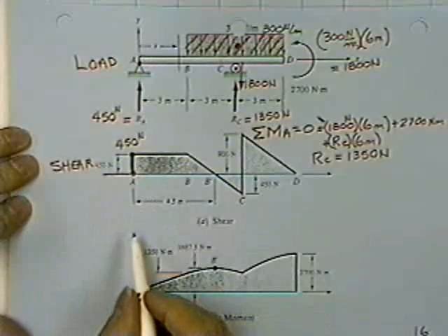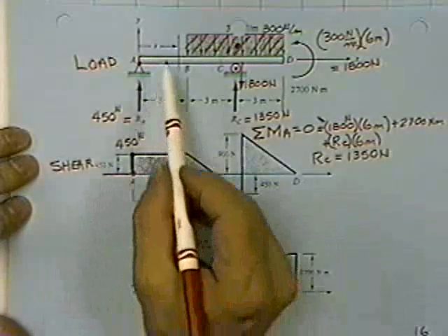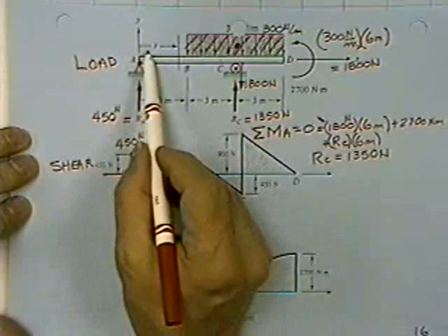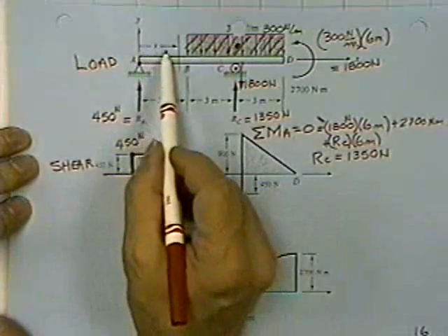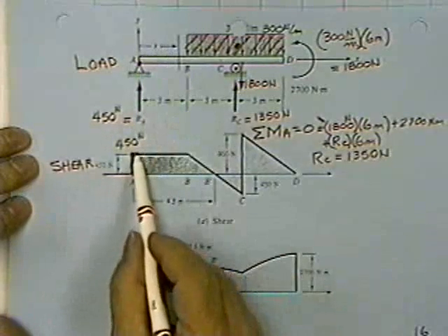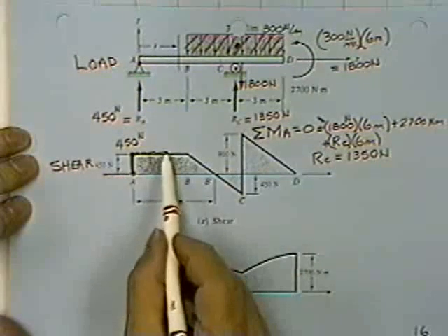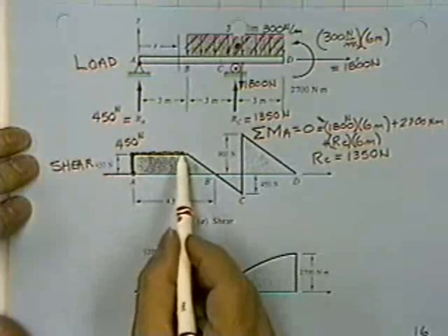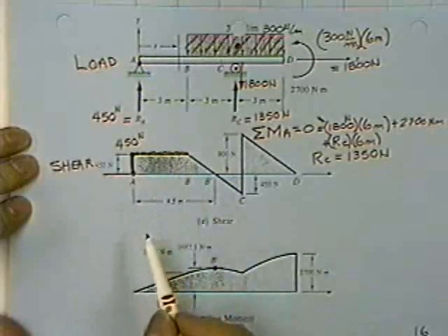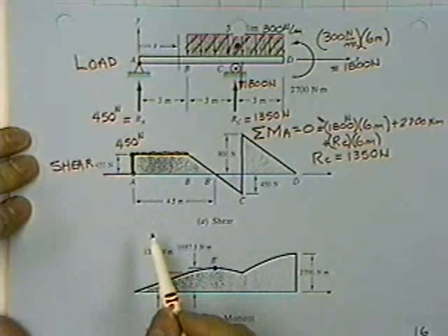Now you continue to do what the diagram tells you to do. This diagram doesn't have anything in this region, and therefore that's what I'm going to do. I'm going to do nothing. I'm not going to go up higher. I'm not going to go lower. Not until I see some new forces acting on the beam above will I move the magnitude.